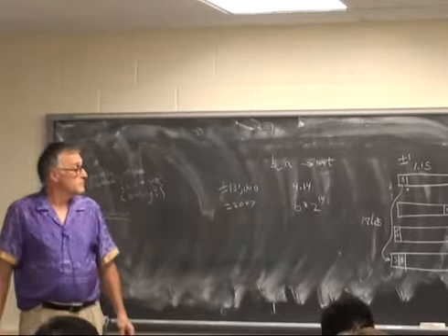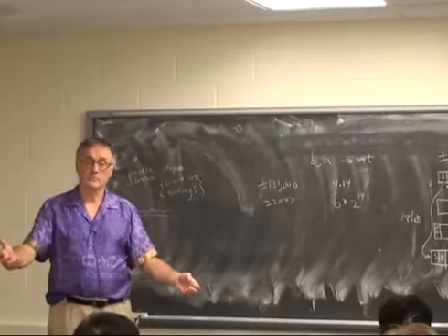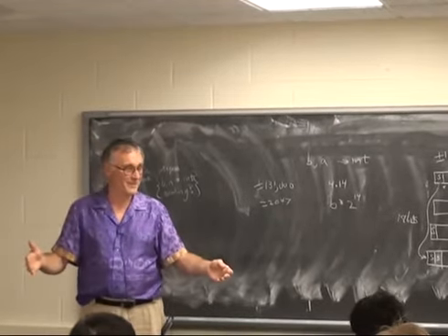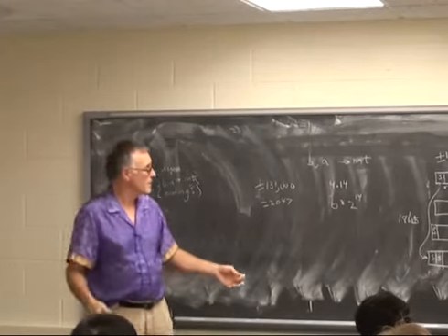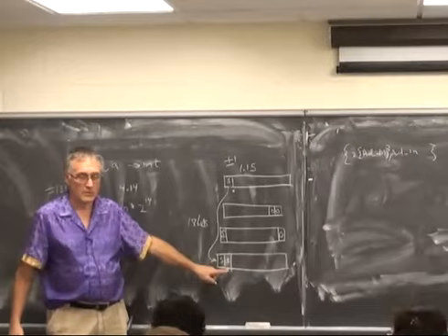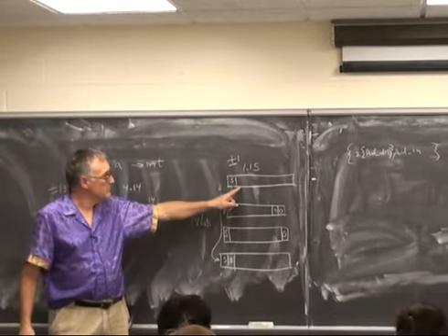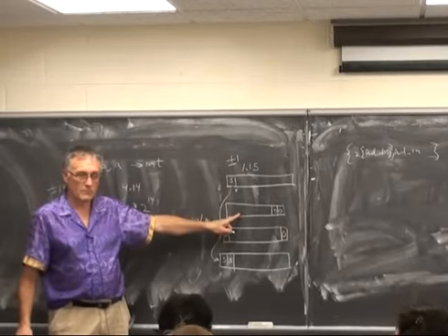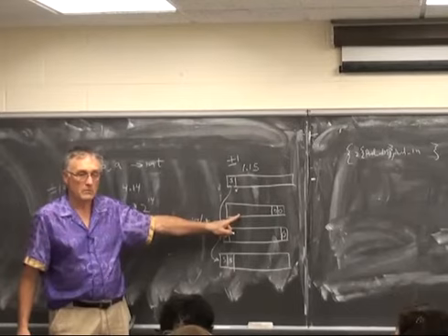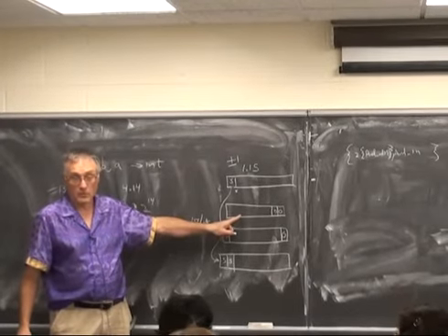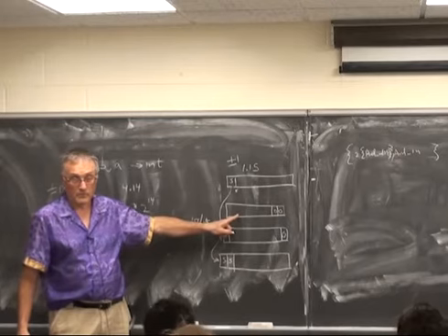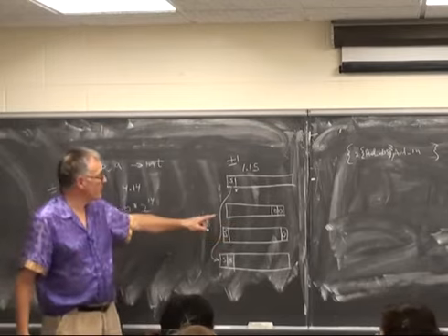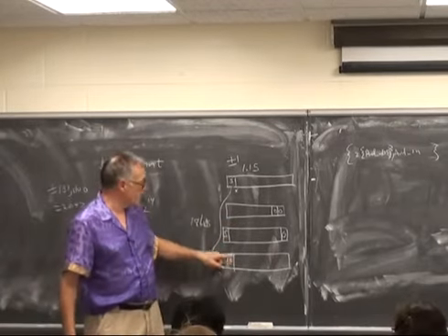What have people done so far? Right justify, left justify, or split the difference? Right justify, it reduces the distortion. But we got some crackling. We're trying to reduce that. It's filtering, but it's filtering with a little bit of distortion. So there may be some overflow. Actually, yeah. There's definitely overflow because at the lower order of the waveform, it kind of peaks out like this. Okay, so if there's overflow, then you might want to go to this situation.